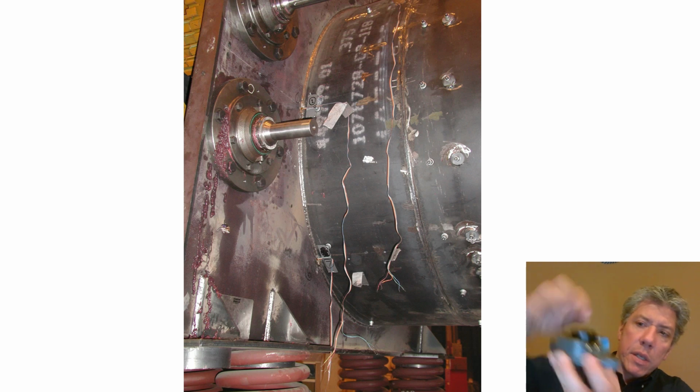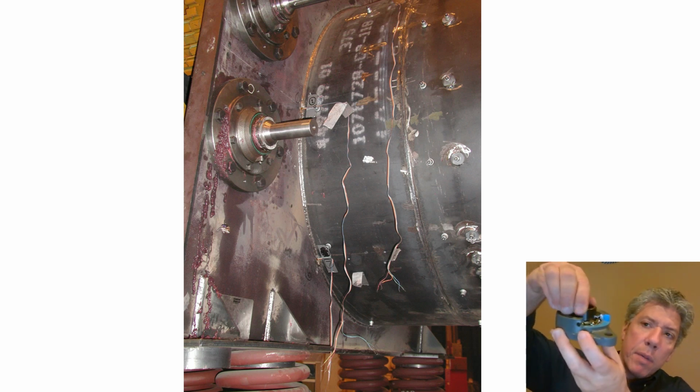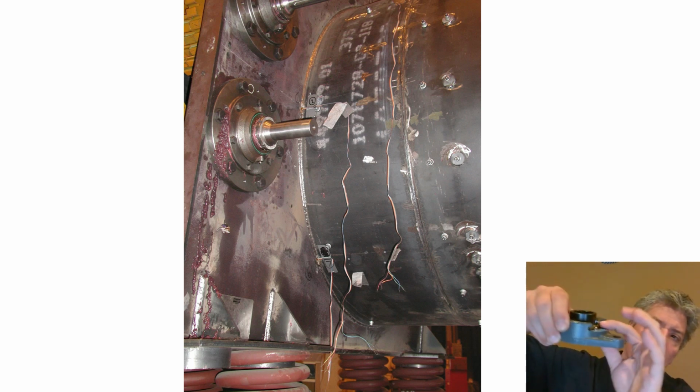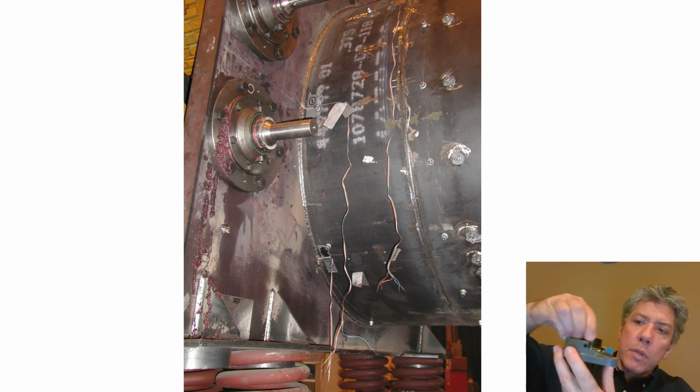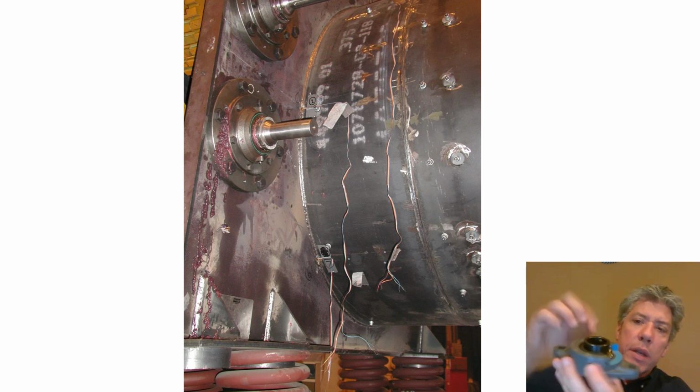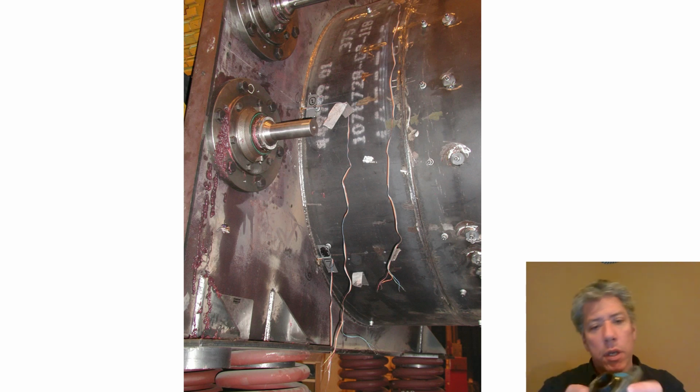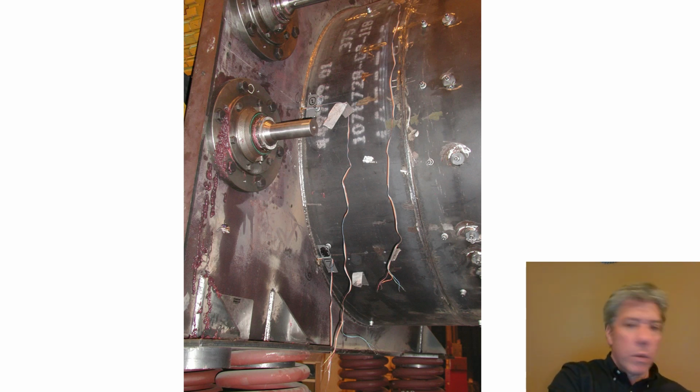There's actually a seal here that's really not supposed to rotate. Maybe you can see that on video. It's got a piece of felt here, and it's supposed to seal the grease in this bearing to keep it from coming out, and of course to keep dirt from going in as well. But those are all what I would refer to as housed bearings, pillow blocks, other types of housing, and they're all typically insert bearings that can be rotated because their outer raceway is a sphere, essentially a portion of a sphere. Here are some pictures of bearings in action.